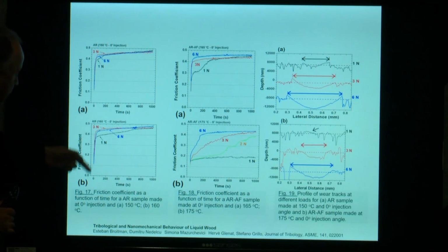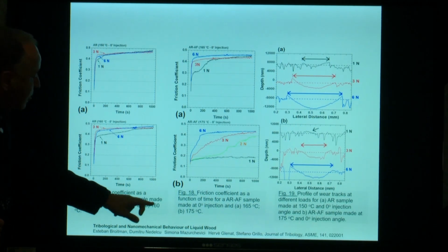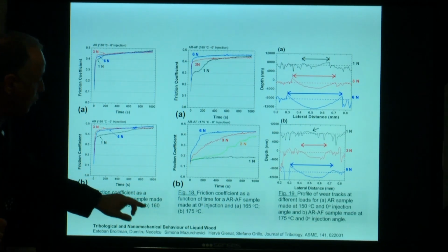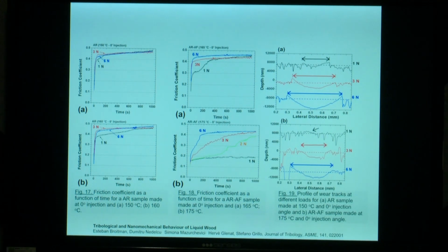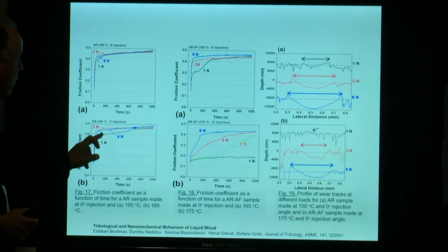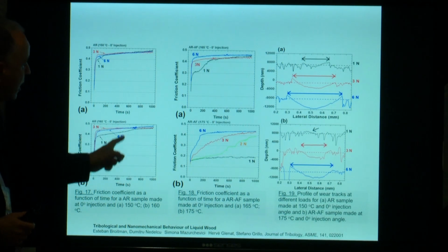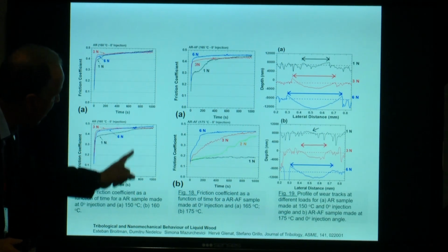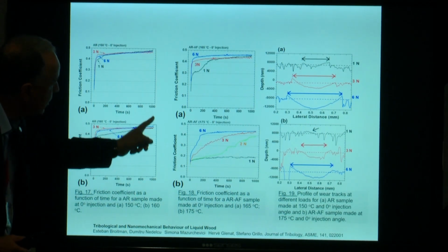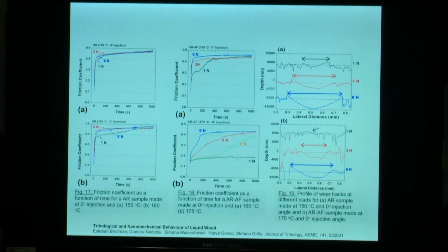Look at another variation of the friction coefficient, in the case when we use 160 degrees Celsius for melting temperature. The behavior of the friction coefficient is a little bit different. It's the same during the first 22 seconds, but afterwards a little bit different behavior, let's say up to 700 seconds, and afterwards they altogether have the same behavior.